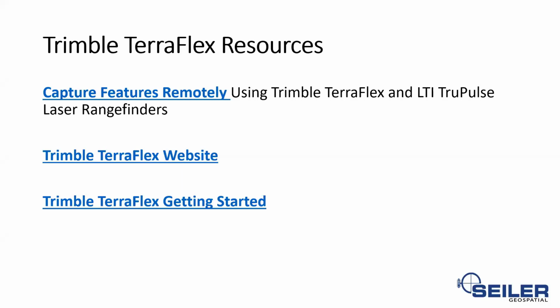Another question that I have here is somebody asked if they can post-process the data with a GNSS shot and use a laser rangefinder if RTK is not available. Yes, you can do this in both TerraFlex and TerraSync. In TerraFlex you can post-process, but you have to use the Trimble Positions application with it to do your post-processing.